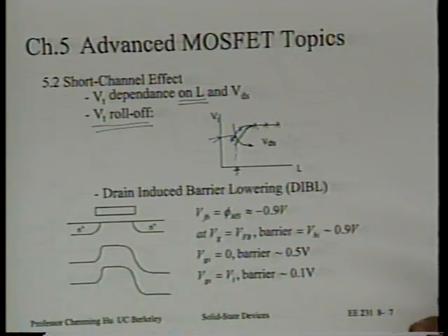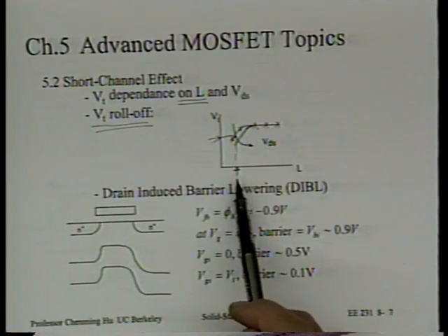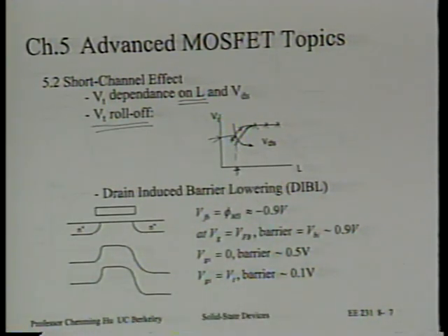So for this reason, even if the lithography was not a limit, there will be some limit on the L that we can use, all right? And so that is a limit, okay? And by the way, today, very often, even in commercial production, our L is no longer determined by lithography, because we can do other things with that particular layer of lithography called the gate length.